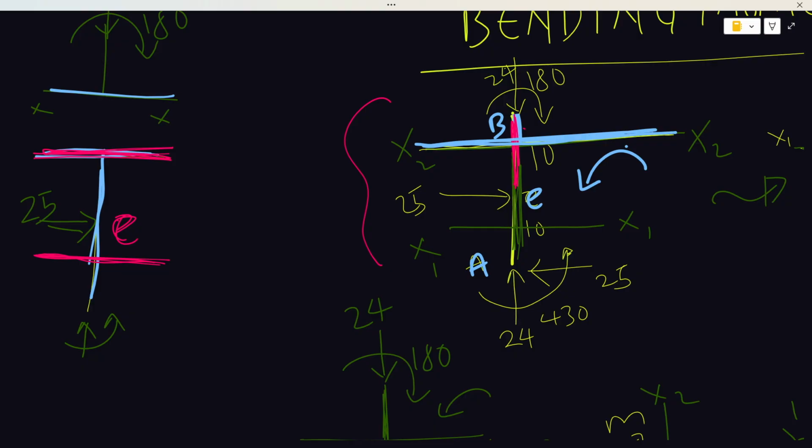That is, to get something in this particular location, I can cut here or cut here. I'm saying this only works as long as what is separating these two cuts is a force, if it is moments you are using it for. Had it been a couple that was here, and you are dealing with moments, you cannot try this any longer.